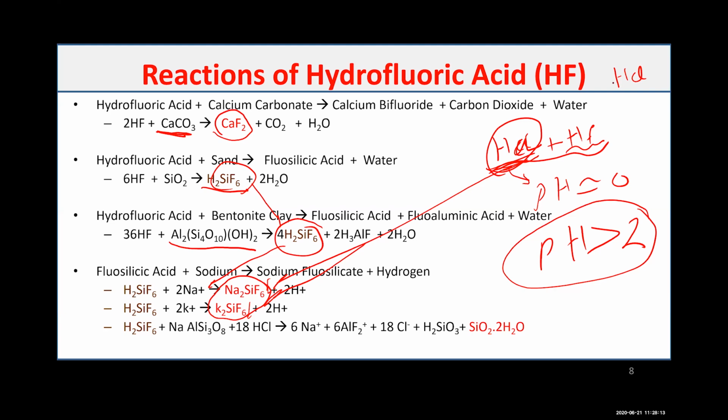The idea here is to dissolve any carbonate before the HF, then behind it comes the HCl, HF to dissolve the silica, and a post flush of usually HCl to keep the pH at 0 and push all the reaction products deeper inside the formation, away from the near wellbore, and in the end you'll have overall enhancement for your production. So I hope that can give a good idea about HF.